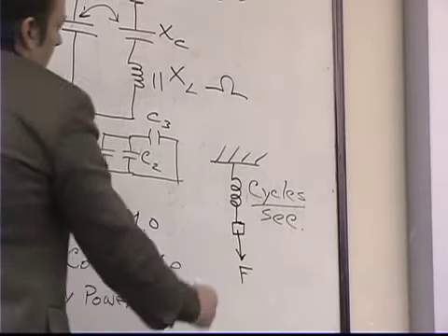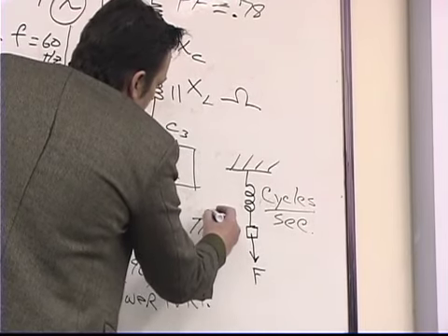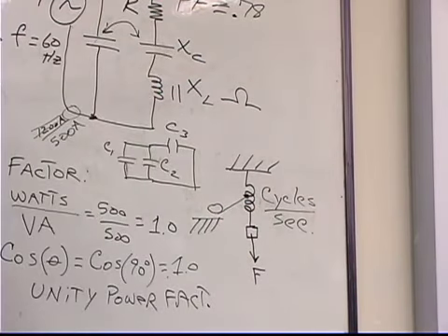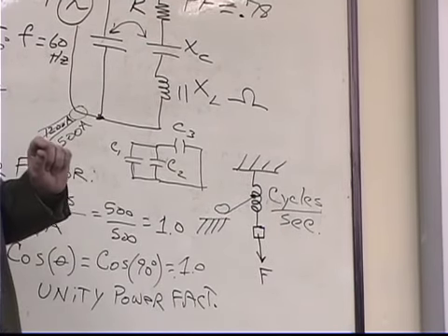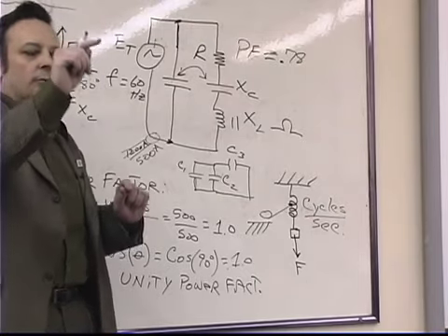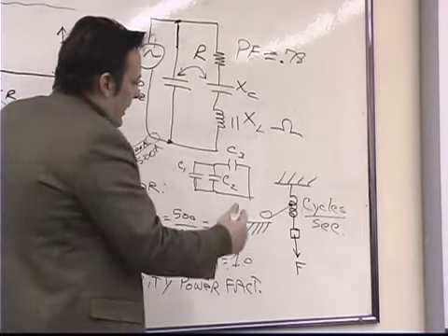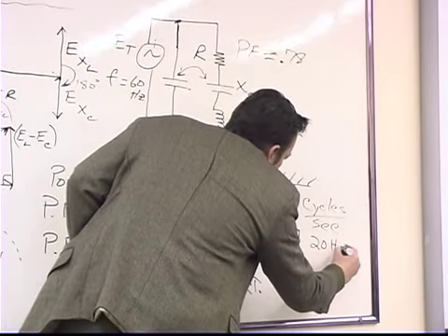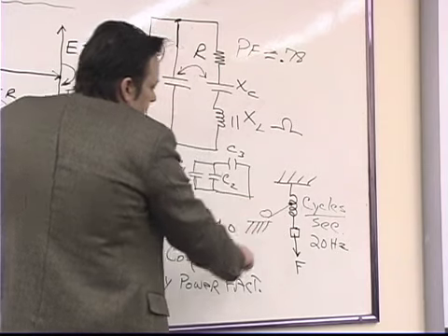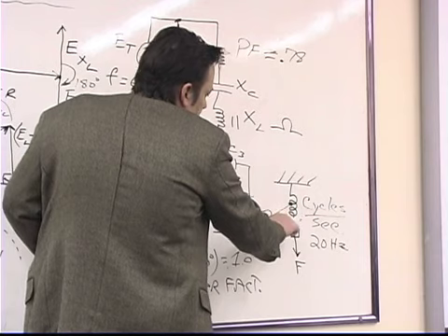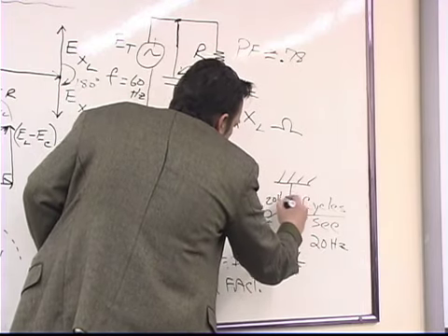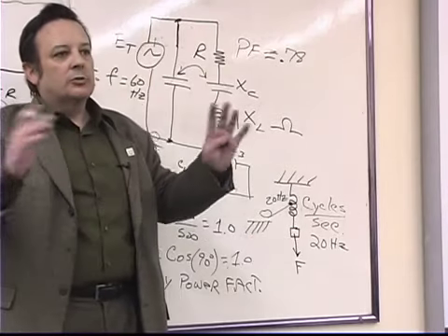Now, if you were to take a motor, take another rigid platform, and take a pulley on a motor and physically attach it to the spring. Take a little piece of twine, wrap it around the spring. So you start tugging on the spring as the spring is moving at its natural frequency. What happens is, let's just say hypothetically that this was 20 cycles per second. That was the natural frequency. Okay? If you adjust the frequency of this string that's pulling down on the spring to the same frequency as the natural frequency of the spring, which would be 20 hertz, what happens is the spring goes crazy.